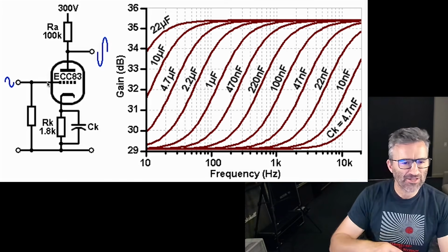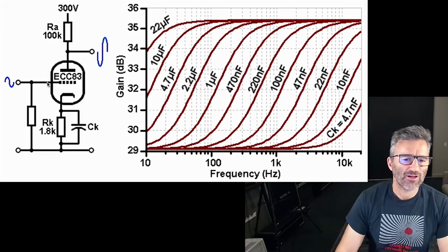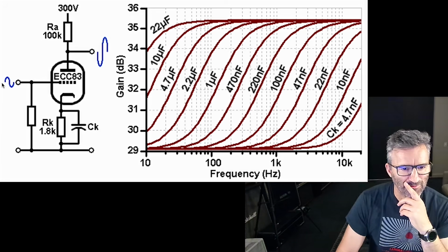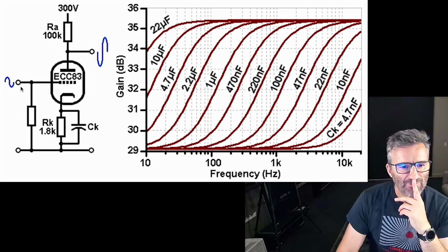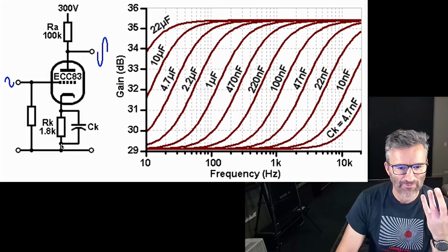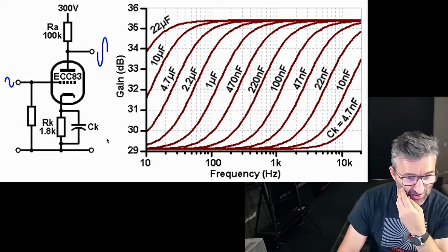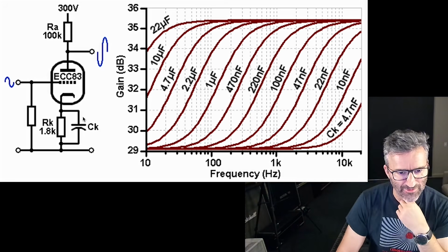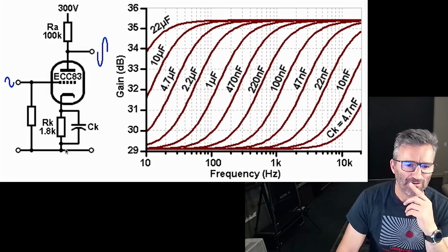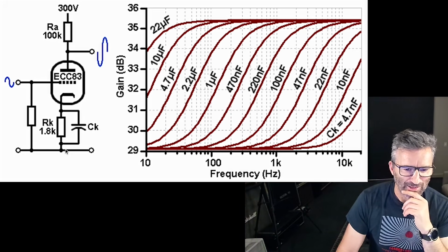Now, as soon as you get an AC signal coming through, which is what, the audio, your guitar signal, as depicted by this little blue sine wave here, well, the AC is actually going to bypass through this guy. Think of it that way, right? It's a bit like a bright cap. It's probably the easiest way to think of it. It actually charges this capacitor, and then this capacitor can release through. And it's just like a bright cap sitting on your gain pot,